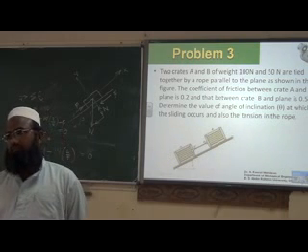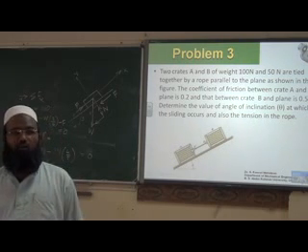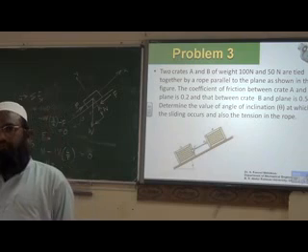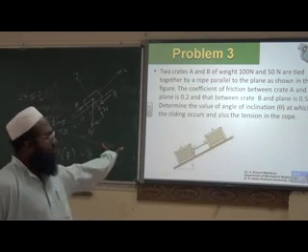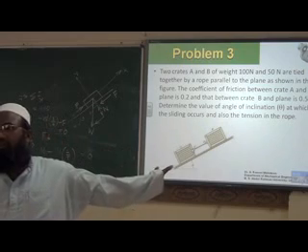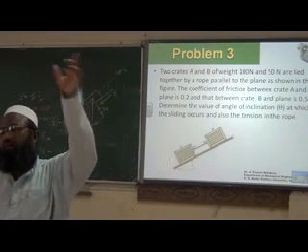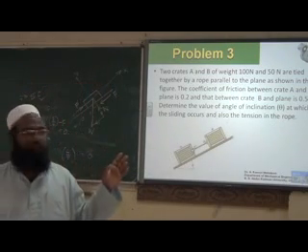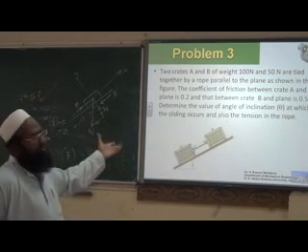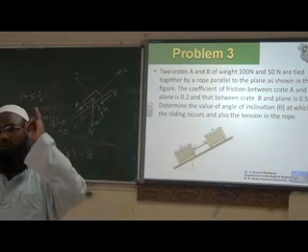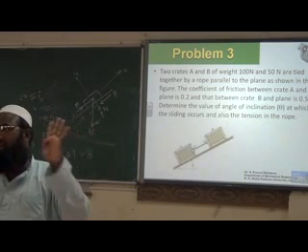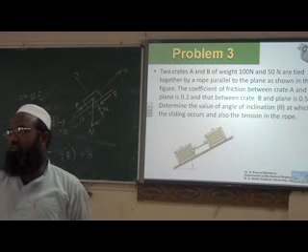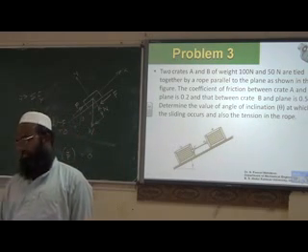Tension existing in the rope CD. So first you consider block A. Draw the free body diagram for block A. Then the free body diagram for block B. We have three unknowns. We don't know what is the frictional force. We know only W. We don't know F, N and also theta. Three unknowns are there. So sigma Fy, sigma Fx equations you can use for solving.